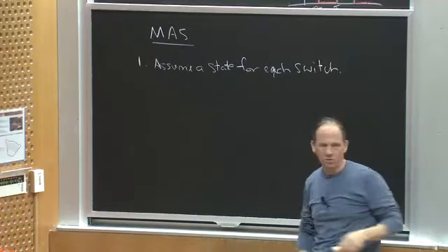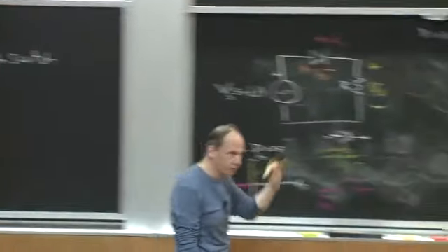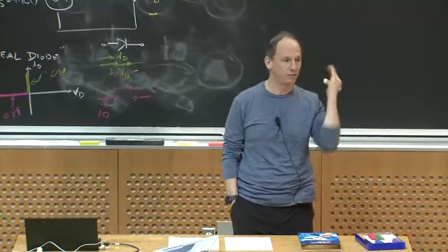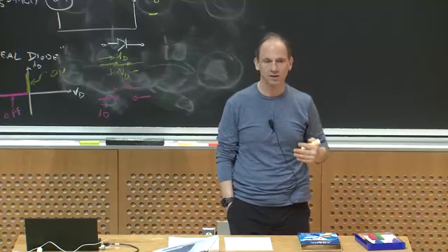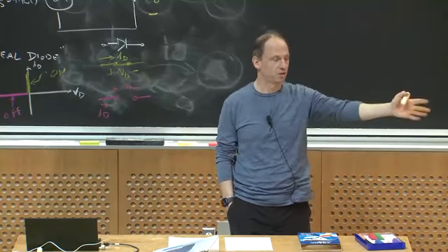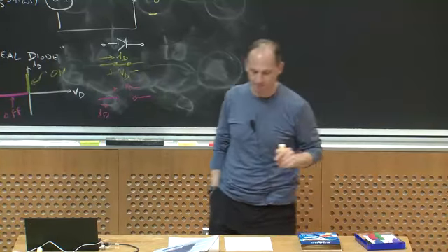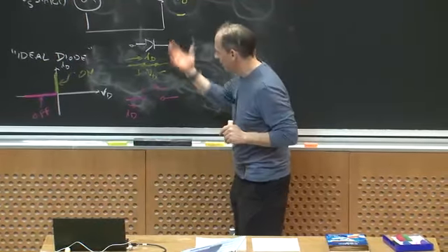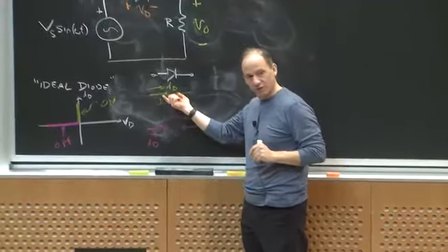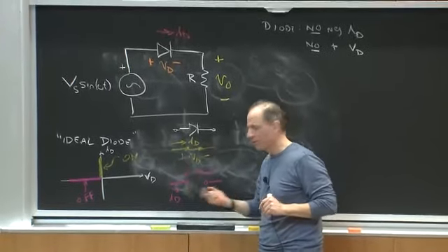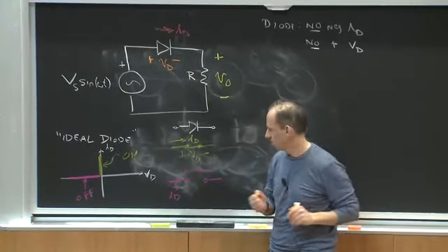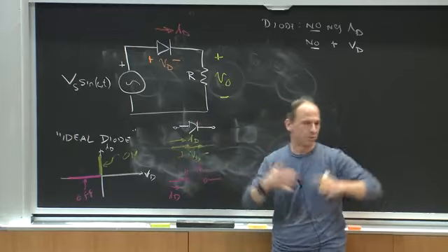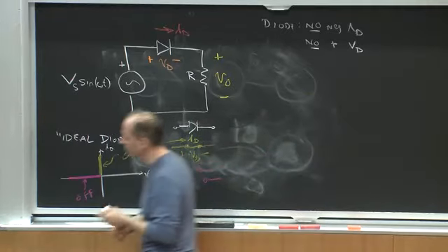Okay? So, some switches, if you fully control the switch, you know when it's on and off because you're telling it to turn on and off. But if you don't know, if you have diodes, for example, in your circuit, guess. Assume it's on or off at a given point in time. Okay? What you would then do is say, okay, take that diode and replace it either with a short circuit if I've assumed it's on, or an open circuit if I've assumed it's off. Okay? And now I've replaced things with shorts and opens, and so now my circuit's simpler.